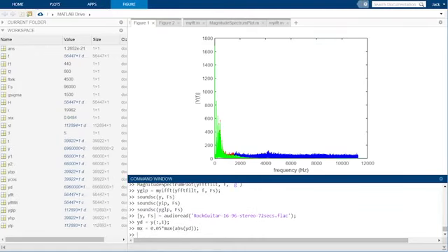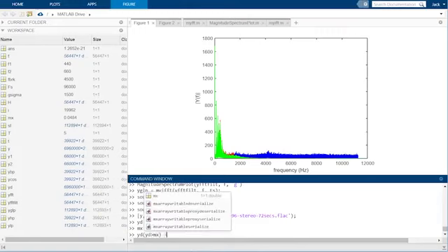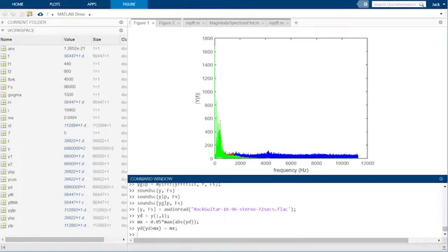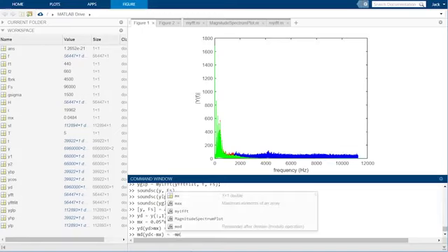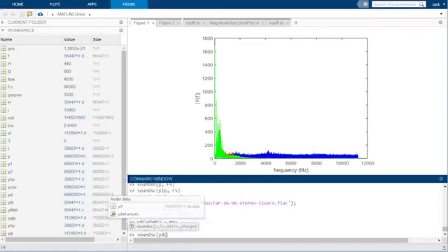Where we clip the maximum value of our signal. And we're actually clipping the magnitude of the signal so that the positive numbers can be no greater than max and the negative numbers can be no less than minus max. We'll listen to a portion of it.